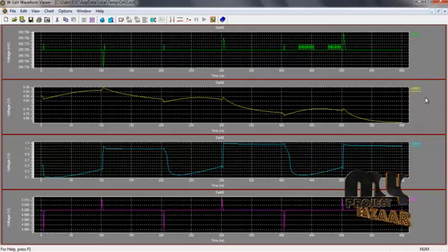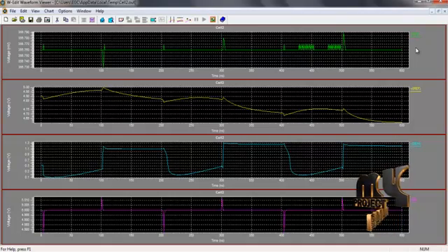VREF is a reference voltage. Vsense is a sensing voltage. Vin is an input voltage of low power oscillator. The Vout, the final output of our product, is fully dependent on the reference and the sensing oscillator. The combination of reference and sensing oscillator will produce the final Vout waveform.